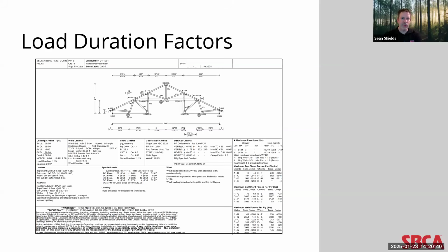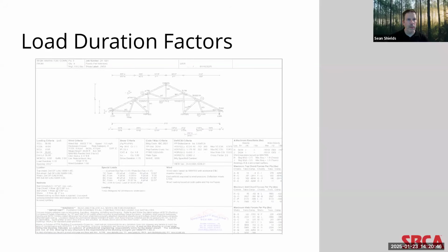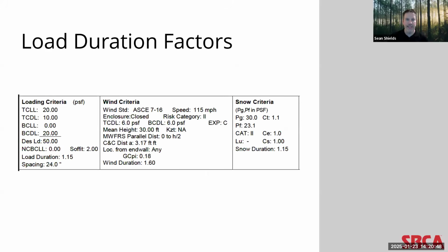So using this truss design drawing as an example, you can see that the combination of the live and dead loads anticipated for this particular truss results in an LDF of 1.15.